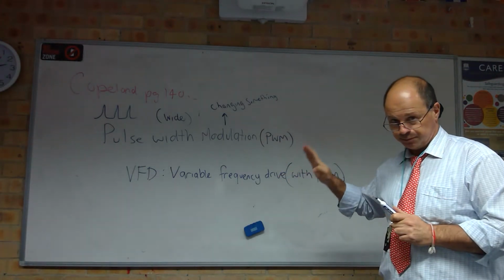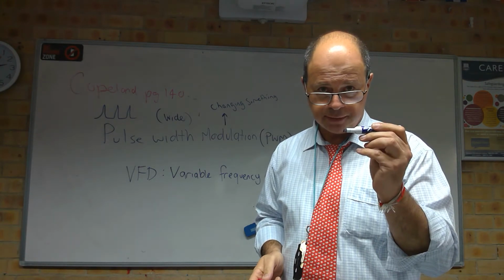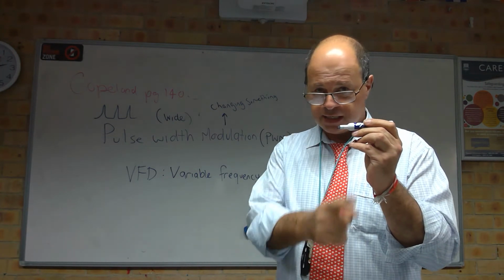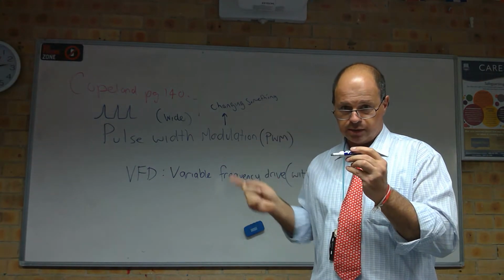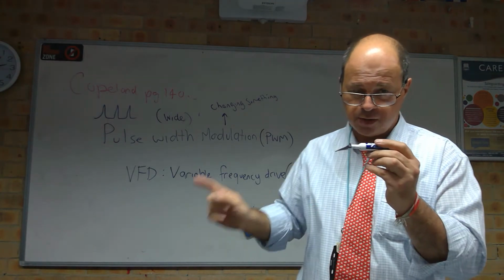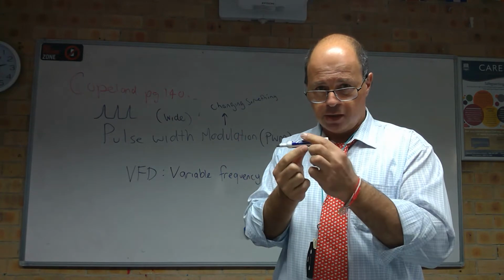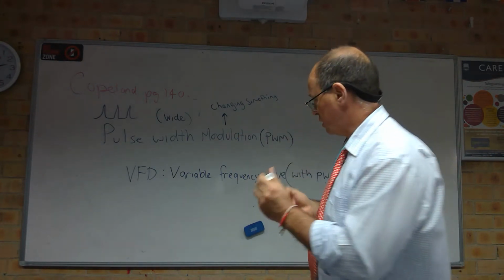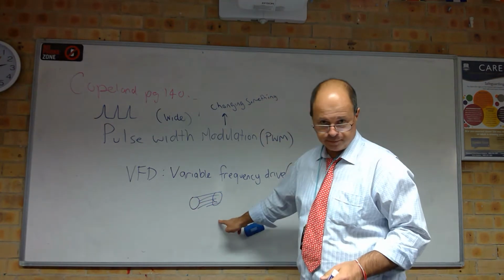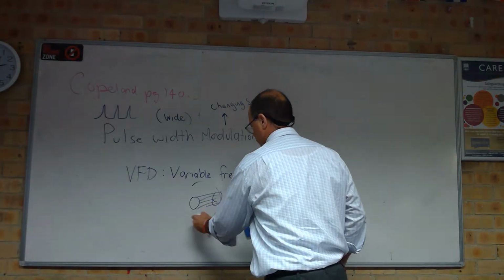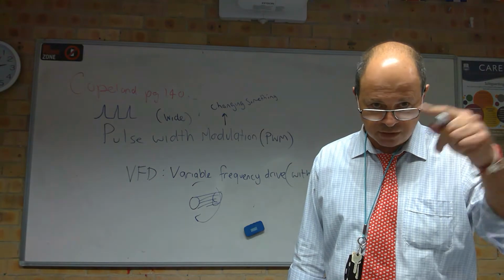Now, for an AC motor, you have a squirrel cage rotor, and we have a stator that's being fed with the AC. Now, it could be a three-phase AC motor or a single-phase AC motor, but both of them basically mean that you have a rotating magnetic field, okay? And that induces a magnetic field in our squirrel cage rotor, which kind of looks like that. And because our magnetic field is going around and around, our rotor chases it, okay? So it's chasing.